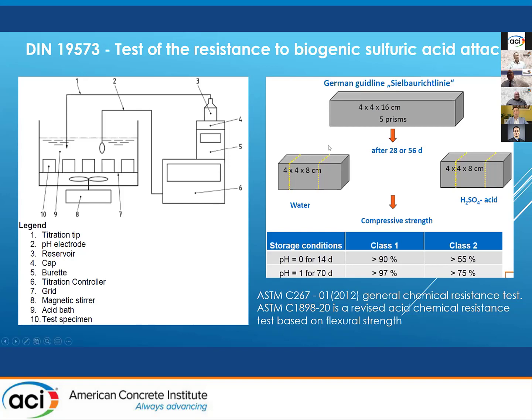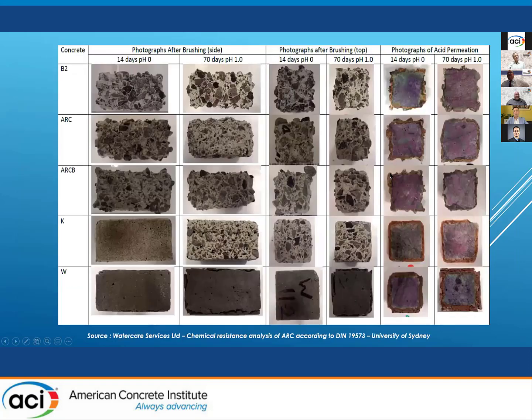The procedure involves, these are all in centimeters, essentially 4 centimeters. So, you know, sort of 1.75 inches by 1.75 inches cross section. And then doing a compressive strength across this little cube that is developed here. So you can imagine it's quite a complicated test, and with such small specimen sizes, you have to be very accurate with doing your compressive strength work.